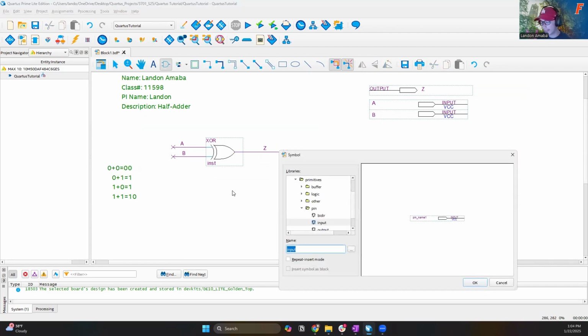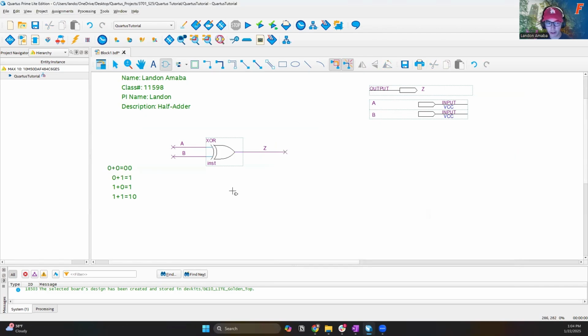So we'll go ahead and add an AND2, a 2 input AND gate. There's 2 ways to do this. We can first drag the input up to A and connect them physically. Connect this one here. And this will take the inputs and power this gate. Or the cleaner, more effective way to do it is create these wires and just give them the same name.